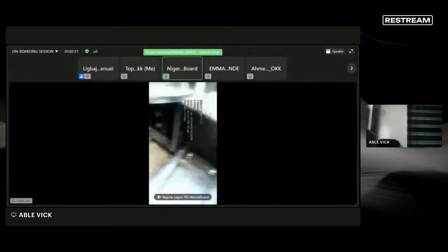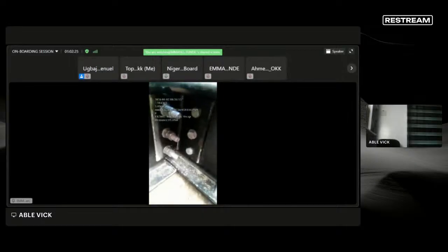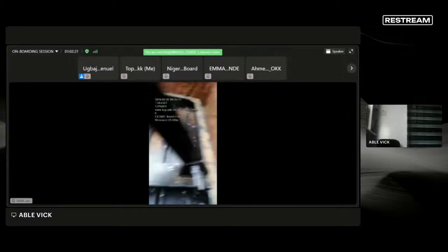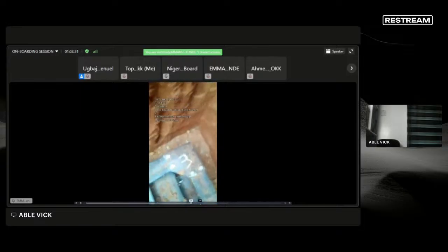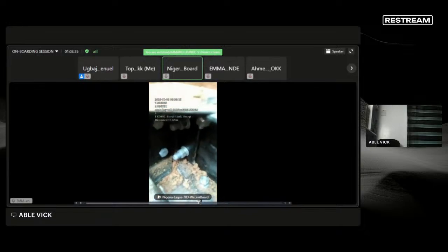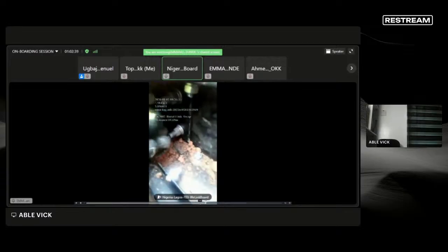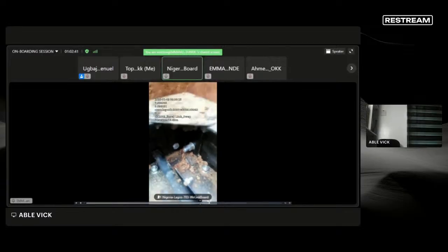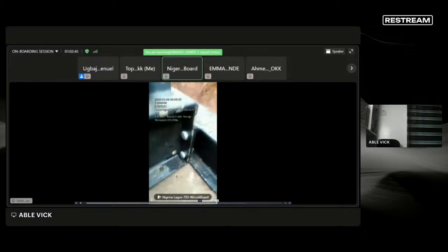So that's what this person is doing. Once it's done, I'll show you the overview of the foundation. And you can see the marking. This is number 3. Then obviously number 4. All the nuts must be completely installed. There must not be any vacant space for any nuts.